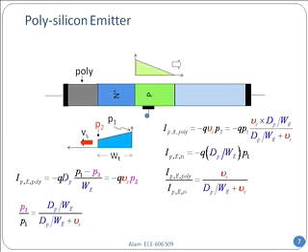Now, as far as electron current is concerned, going over from the emitter to the base to the collector, well, no problem, because I haven't really changed anything. There's no poly over there in the junction. And so in that case, I will simply write the same expression, N1 minus 0 divided by WB, that is dN dx, and then Q multiplied by dN. So therefore, I will have that current and correspondingly the N1 value. You already know that N1 value. So therefore, I am ready to compute the gain in the presence of polysilicon transistor.